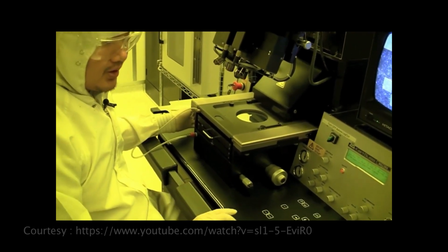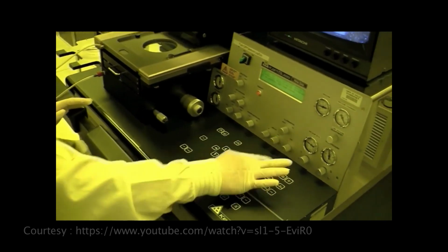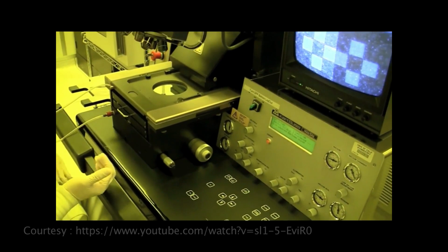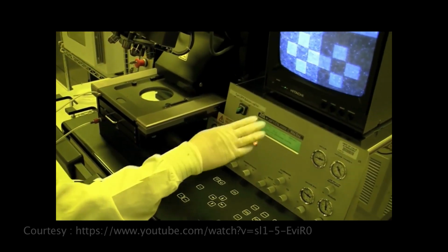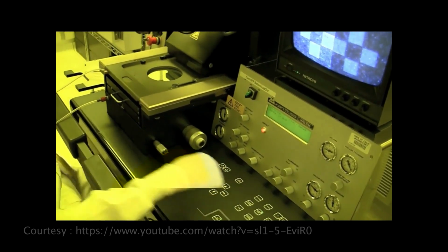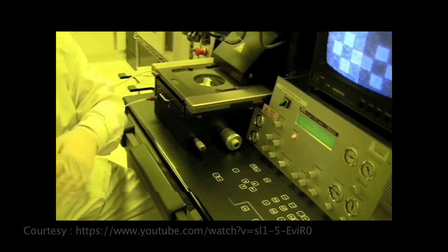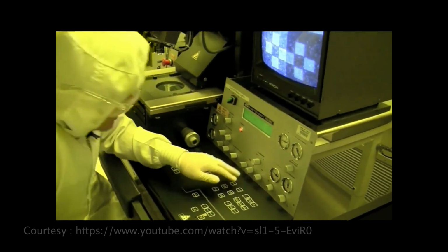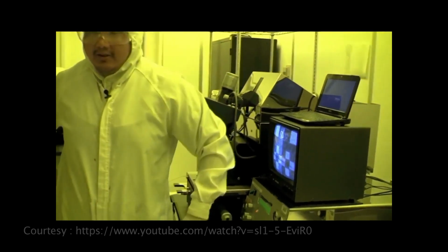And how do you expose? You press alignment check first, which will bring it up to touch. You want to make sure nothing moved. And then when it's in contact, you hit exposure. When you hit exposure, it's good to turn your back away from the light so it doesn't damage your eye. So we hit exposure, and then we just turn away.